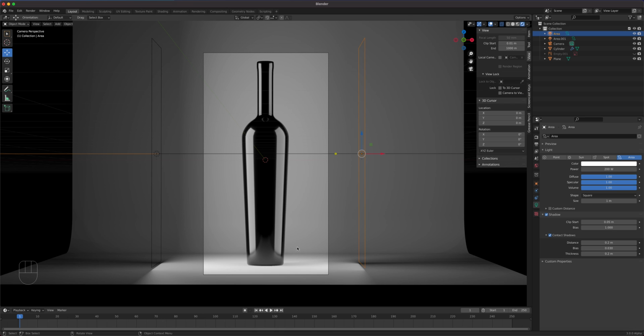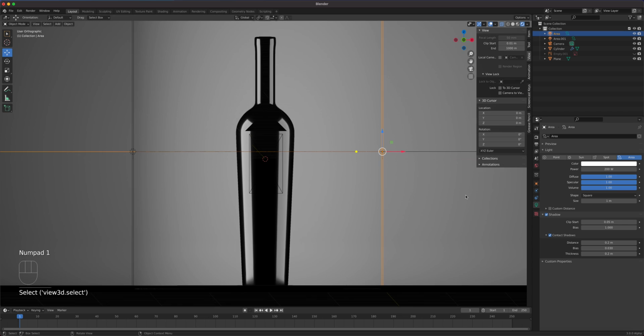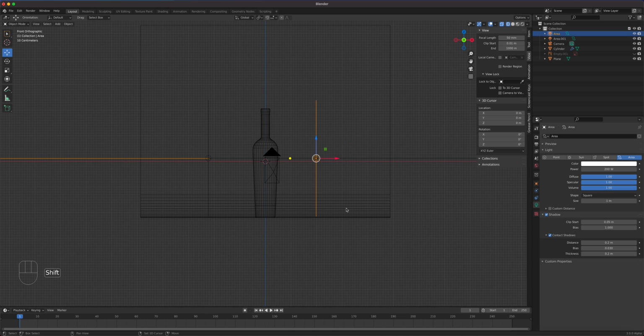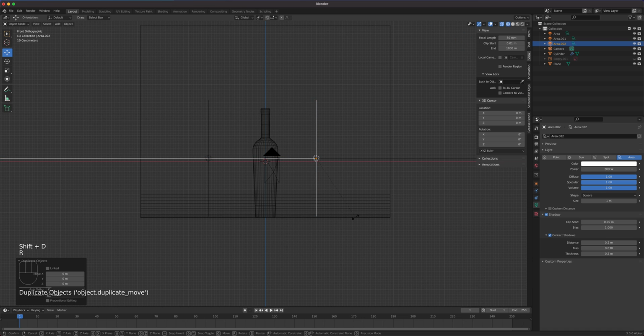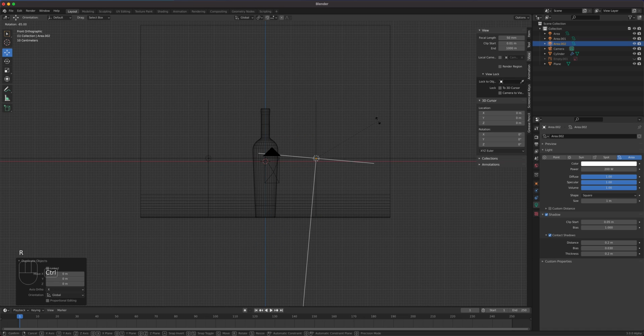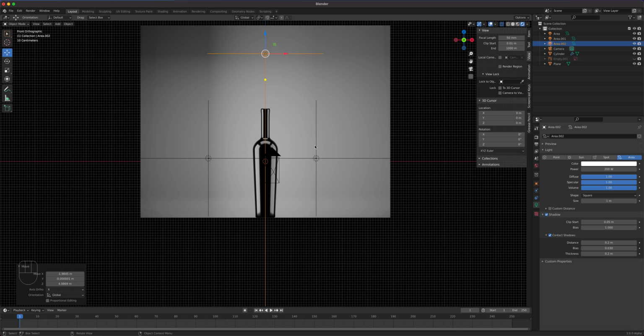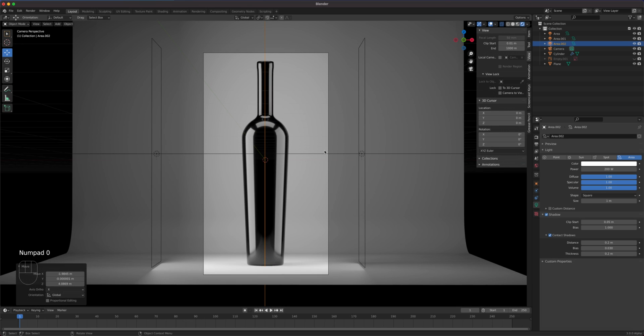All right, and we're still getting some shadow on this one, maybe because we're way too close, or we need one more light at the top that just controls the lighting here. So I'm just going to select the same light. This one is the 200 watt one. Let me go to the front viewport. Okay, go to the wireframe so you can see. I'm going to duplicate that again. Okay, and then I'm going to rotate it, hold down Control so it's pointing down like so. Then I'm going to bring that up, pressing G right here. So let's take a look at what that did. All right, let's press 0 so that the camera is factored in. All right, so we're still getting some cuts right there on that shadow.